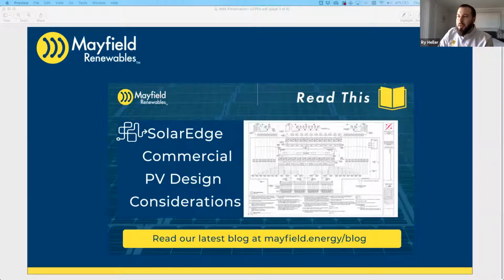Sure. I think as the blog goes into, the focus is where we have inverters that can take 3 strings, like the large 66 or 100 kilowatt inverter or the 43.2. They can take 9 strings, but it's really 3 strings per unit.